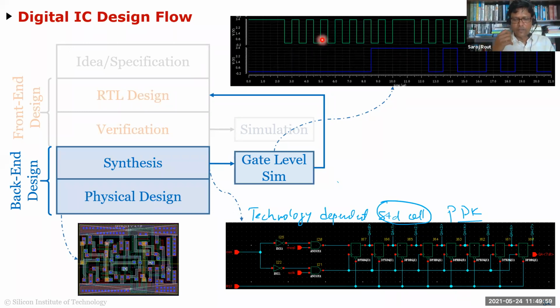So to answer your question, for physical design, if it is a full custom design, physical design means layout. That's it. You're just using a layout editor to do layout. If it is a simpler design, all it means is you just do placement and a little bit of routing. That's it. If it is a complex design, then chip partitioning, placement, routing, clock tree synthesis, and timing are all done through one tool, or sometimes one suite of tools. Okay, did that answer your question?